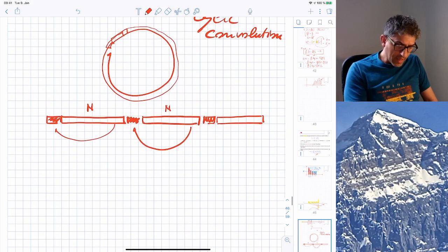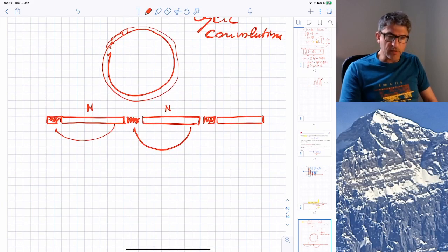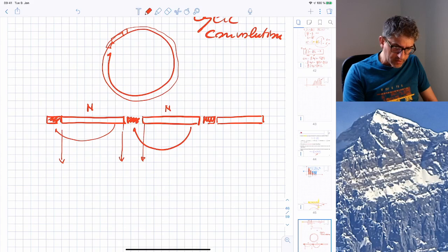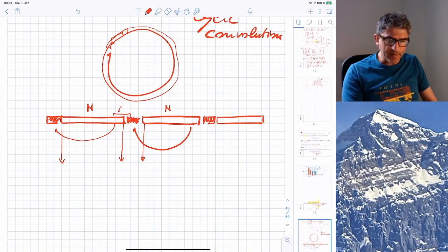And then, as we send this sequence through the channel, we only sample from here to here. Then you see these symbols, from the last symbol here to the first symbol here, contain garbage because the impulse response will overlap with the previous block and then the next one.